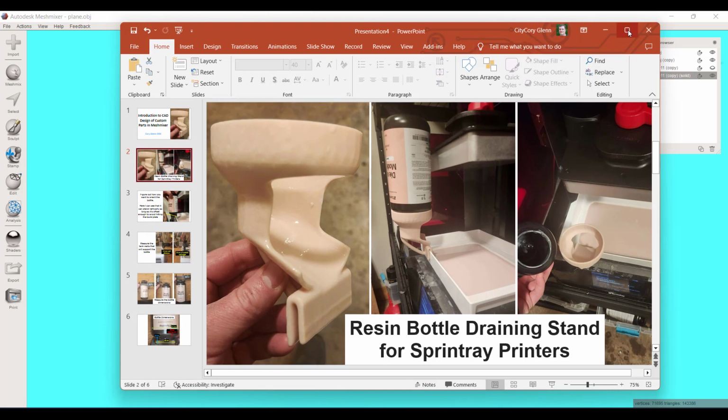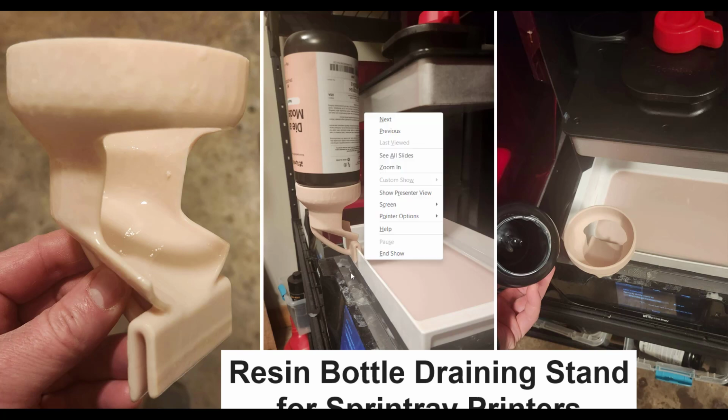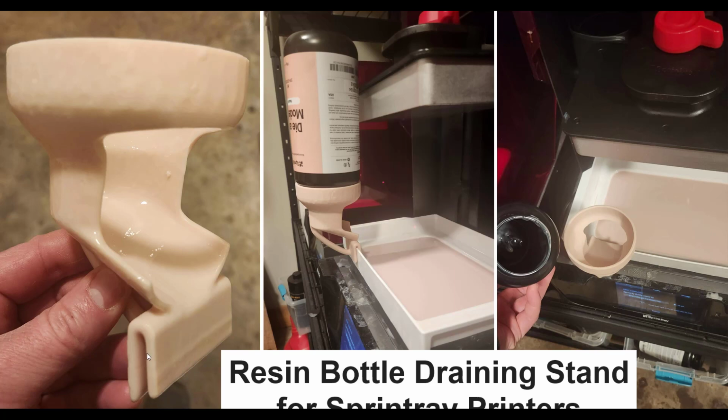Now, this should be designed to just hold a nearly empty bottle, but occasionally someone might put one that's got a higher amount of resin in it. Maybe it's a half full bottle that they're draining. So it needs to support a little bit of weight. And because this is basically what's supporting it all, I want to make these walls right here that you're seeing thick enough that they can resist that force if you have a heavier bottle. So I don't remember what I did when I did this.